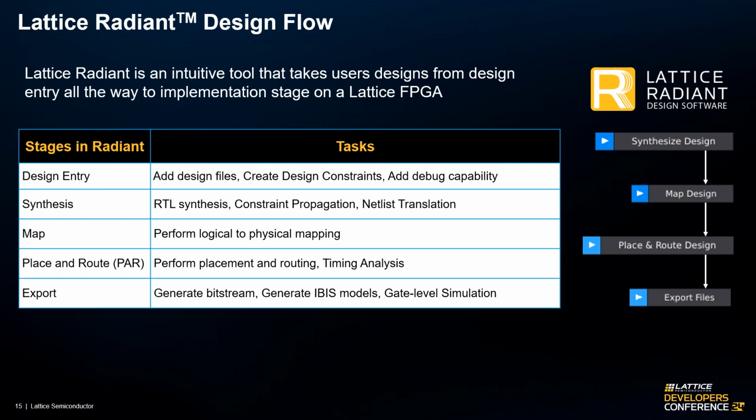Finally, in the export stage, a bitstream could be generated and downloaded to the device using a configuration programmer. Optionally, IBIS model and gate level simulation files can also be generated here to verify the functionality of the design.